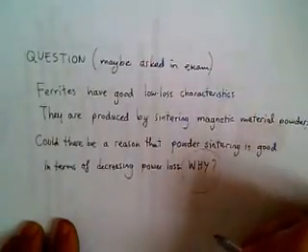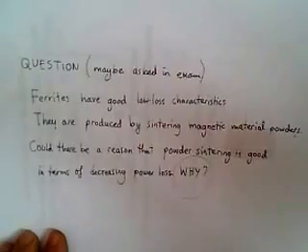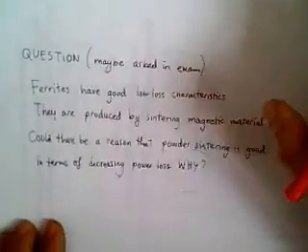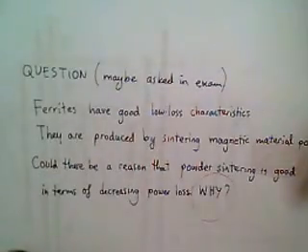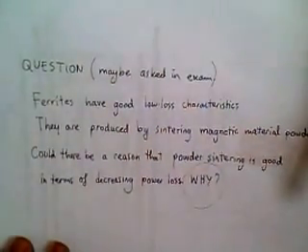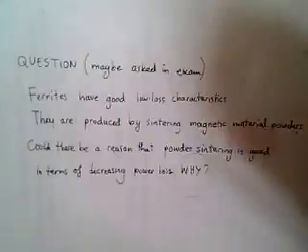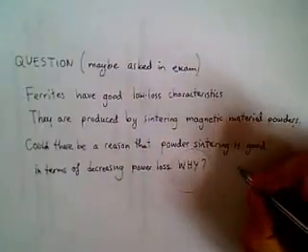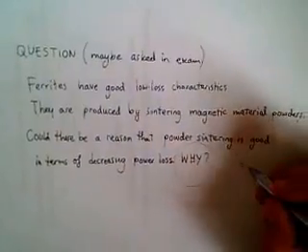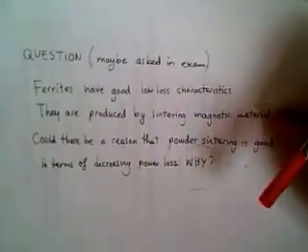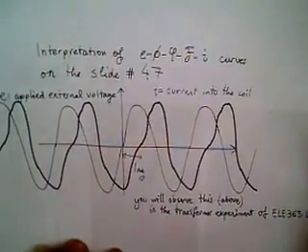You may ask why. Why does powdering and powder sintering create those efficient low loss magnetic materials? The answer lies within the eddy current loss, because the powder is a limited volume and the current is confined, and the I squared R loss is small compared to high volume circulating currents.